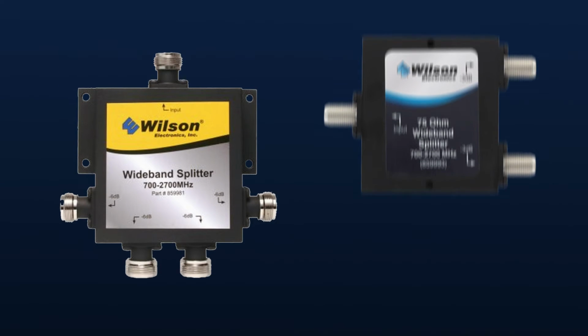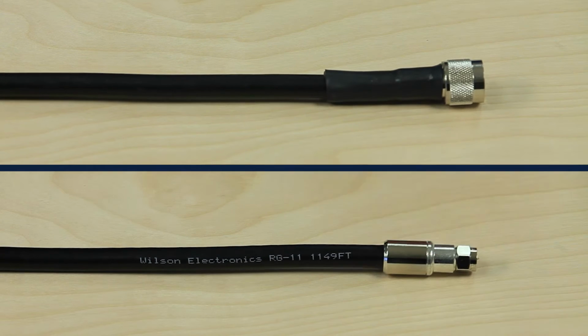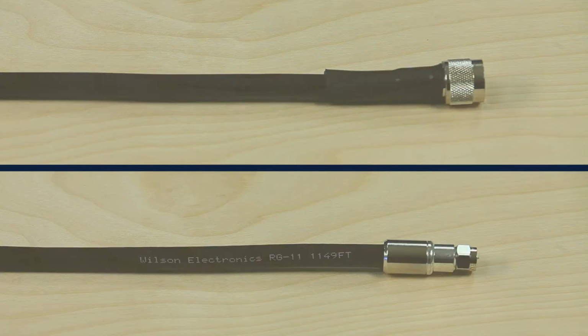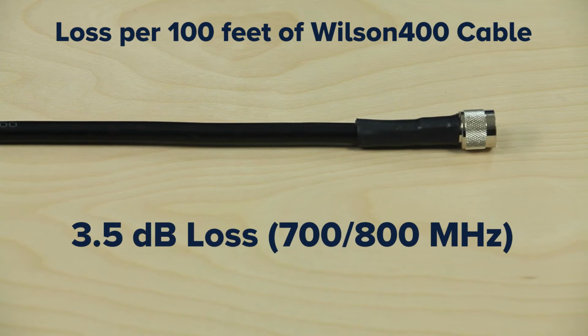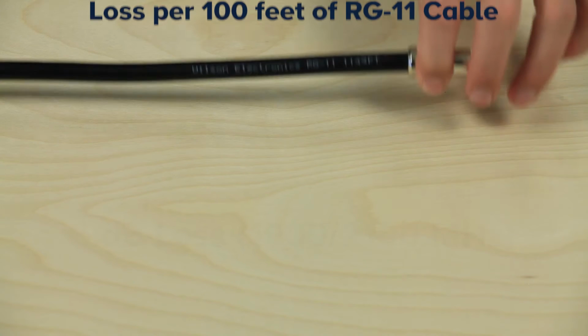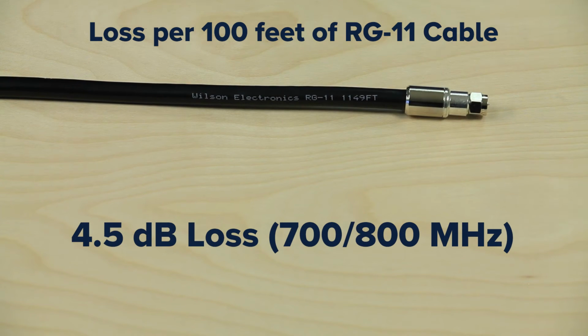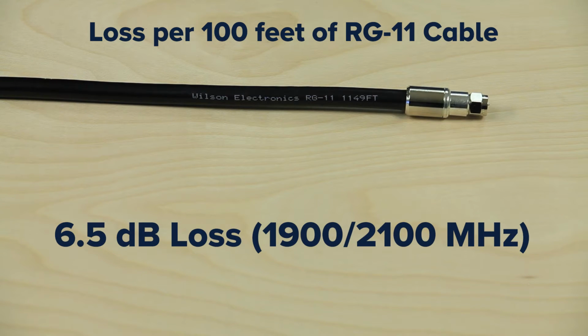System loss is all the loss from cable runs and accessories. Depending on the cable you are running, there will be a different amount of cable loss. For every 100 feet of Wilson 400 cable, you'll lose 3.5 dB of signal on the 700 and 800 MHz frequencies and 6 dB of signal on the 1900 and 2100 MHz frequencies. RG11 cable has a loss of 4.5 dB per 100 feet on the 700 and 800 MHz frequencies, and 6.5 dB of loss on the 1900 and 2100 MHz frequencies.